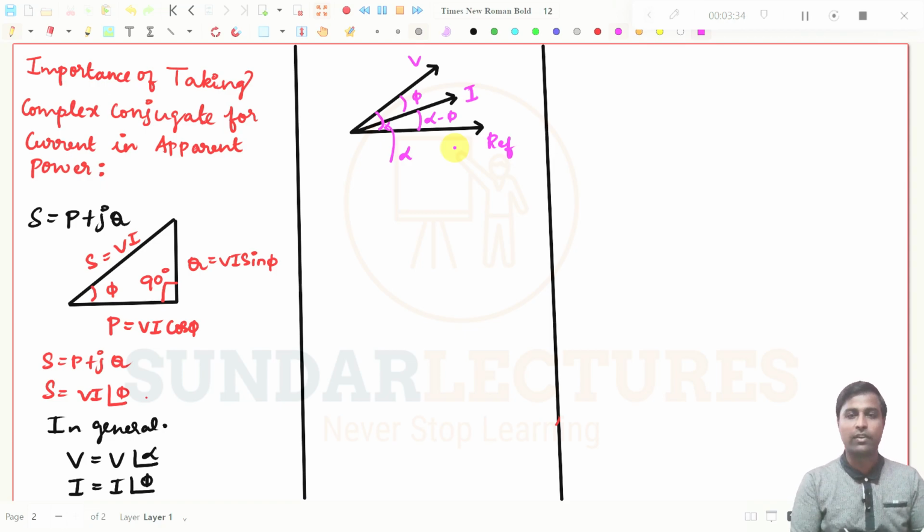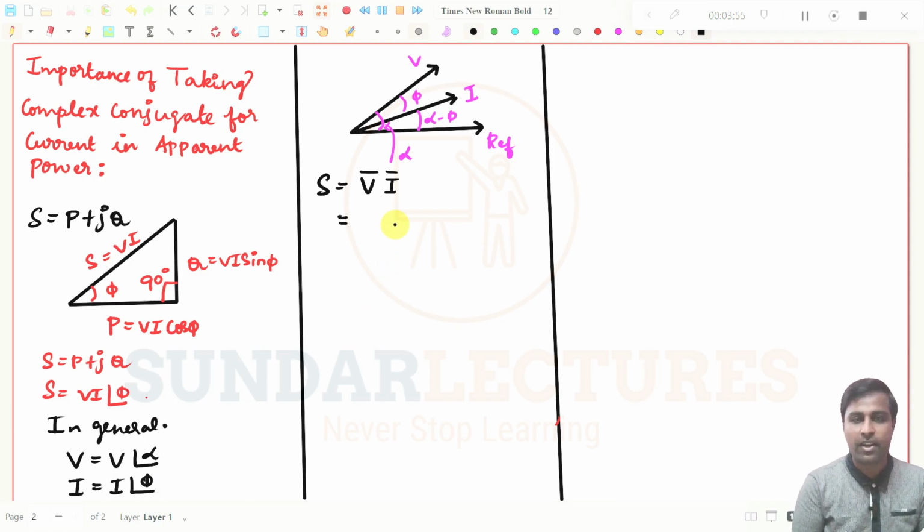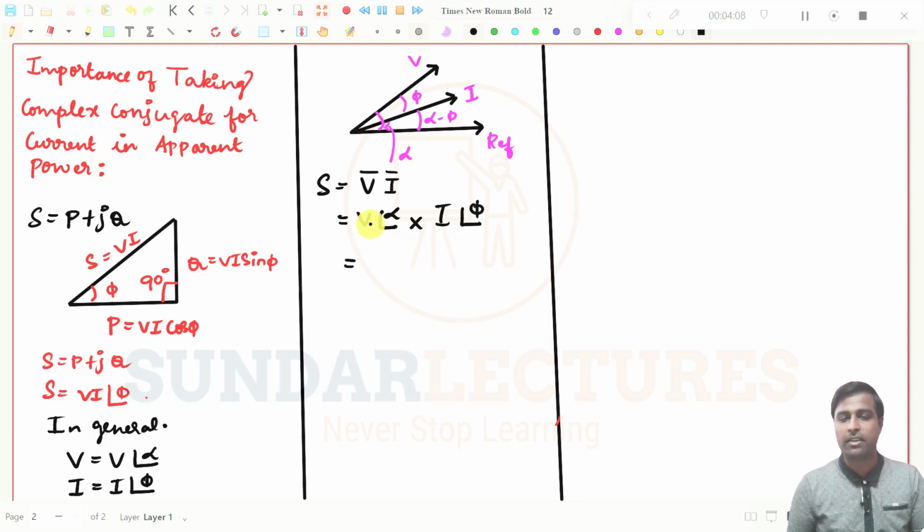So now we will go for the expression. The apparent power, that is the complex power S, will be equal to V phasor into I phasor. I am not taking the complex conjugate here, to explain to you. If you are not taking the complex conjugate, what is V here? V is V at an angle of alpha, into what is I here? I at an angle of phi. This is the value. And if you multiply these two, what will you get?